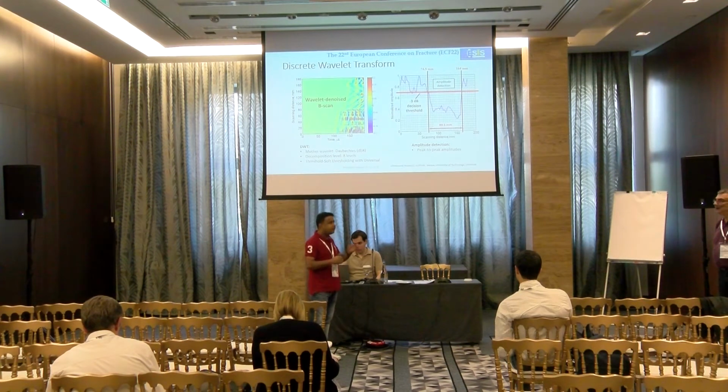And when the guided waves pass through layered structures, the modes can be converted. That is why the phase velocity sometimes cannot be measured from the 2-dimensional fast Fourier transform, which is quite common for measuring the phase dispersion curve. But it is not possible. So that is why we have to filter out the reflected waves and consider only the direct waves, and then we apply the VMD and HT to estimate the time of arrival and phase velocity.